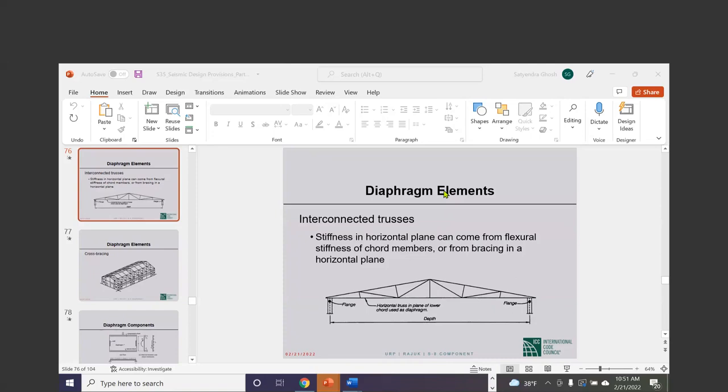Okay, Dr. Ghosh. While calculating soft story effect, should we account for the stiffness of the story below grade beam, that is basement or surrounded by soil? There is nothing called soft story effect that I know about. You deal with soft story the way it is. It is a stiffness discontinuity by definition. Quite often, soft story goes together with weak story. There is also a strength discontinuity.